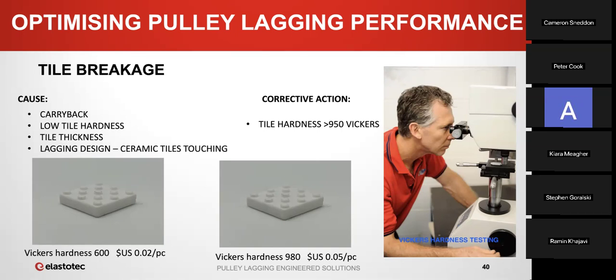It's made from a material that's been filled, and the downside in operation is that the dimples will break off. You can actually have dimpled lagging and find where it's almost smooth because the dimples have just gone. You know, they've just been removed. You can actually also wear through these ceramic tiles. Very, very important when you're looking at ceramic lagging, if you want to specify or choose something, that you need to at least find out the quality of the ceramic that's being used.